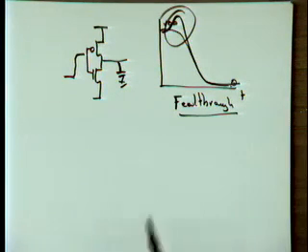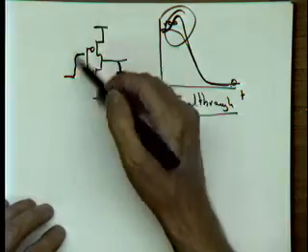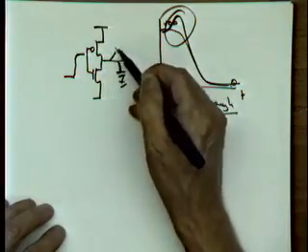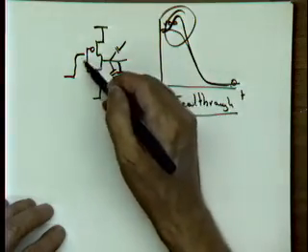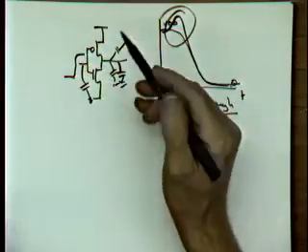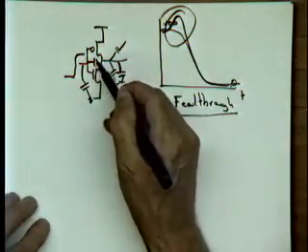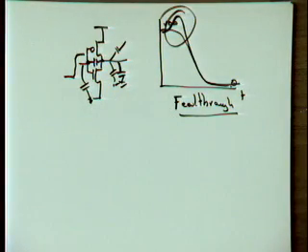And it has directly to do with something I'm going to discuss in a minute when we talk about capacitors. If you think about the capacitances of this gate, well, there's the capacitors to ground at the output here, which are your diffusion capacitors. This input node will see some capacitor to ground, which are your gate to source capacitances. But remember, there's also a capacitance that sits between the gate and the drain of our transistors, the gate to drain capacitance.